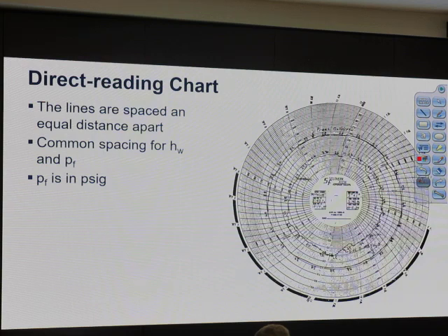With the 80% limit, you allow yourself some room for slugging. Gases will go through there and slug. If you hit a slug of gas, it goes off the chart, literally, and you let gas pass that you haven't measured. So you want to stay on the chart and allow some room for it. That's where the 20 to 80 came from when those charts were established.